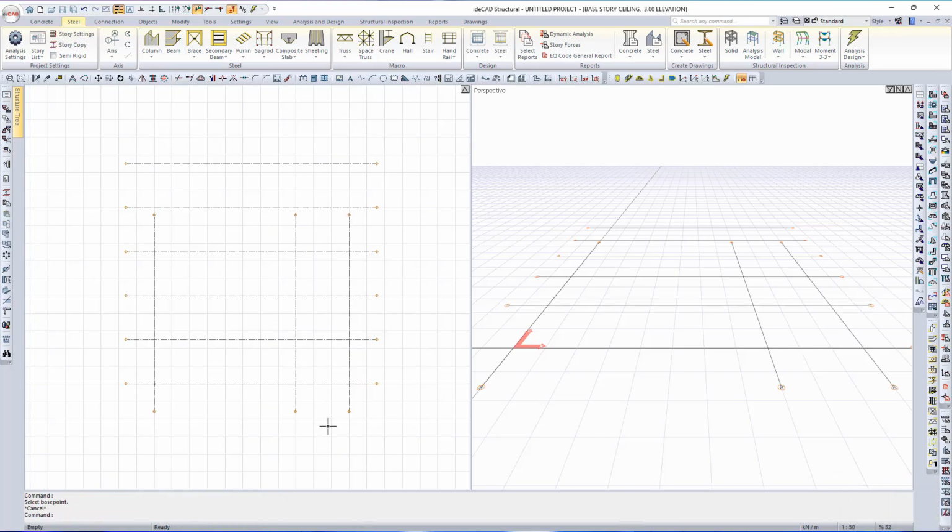Now, as you can see, the plan is starting to look a bit cluttered. When entering geometry, it helps to tidy up the workspace for better visibility. There's a helpful feature for this. If you go back to the axis section, you'll see a small arrow next to the icon. Clicking it opens a drop-down menu, where you'll find contour lines and calculate contour options.